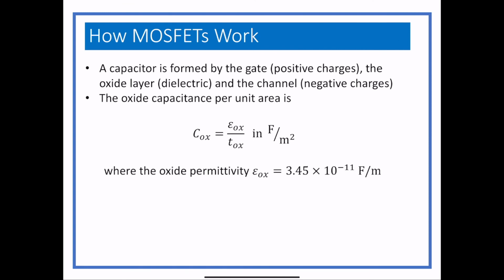So we can calculate the capacitance. However, when we talk about capacitance, we're not really finding capacitance, we're finding capacitance per unit area. So don't make the mistake of thinking otherwise. Sometimes a C prime is used, but oftentimes it's just called capacitance, but it's really not in farads. It's really in farads per square meter. Unless you know what the width and the length is, then you can say what the capacitance is. And we know what the permittivity of the oxide is, so that's not too difficult.